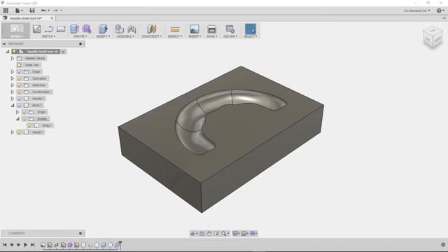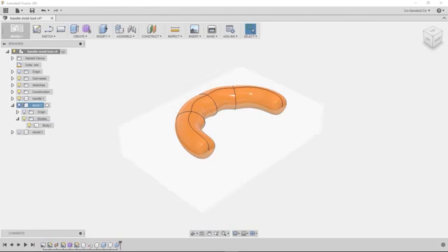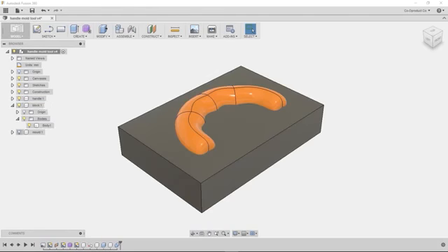So we're going to look at manufacturing a mold for the handle that we designed earlier. We've actually created a mold block simply by, if I just turn some parts off here, I can show you. Got the handle, then created this block, and then combined the two entities. Then we take away the handle, and we're left with the mold tool.